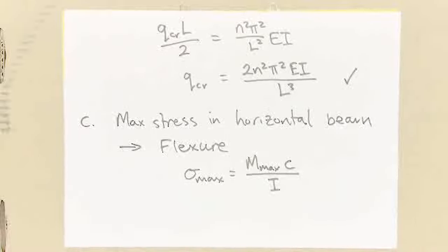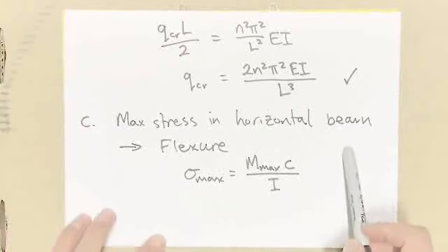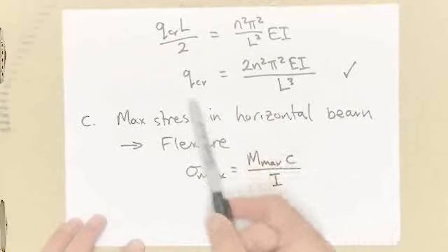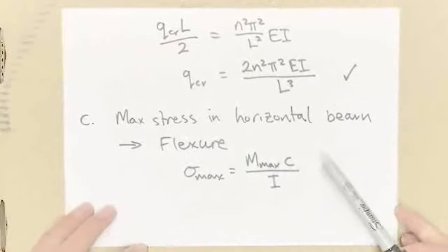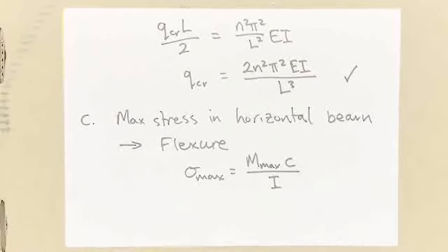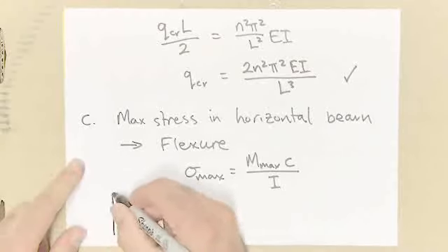Then it doesn't finish there. It says the maximum stress in the horizontal beam, what does it say? Just before the columns AC and DF buckle. So just before the load, let's say, when the load is this value. The beam is rectangular, and it gives you the cross section in the question, 40 millimeters by 20 millimeters, height times depth. So the cross section looks like this.